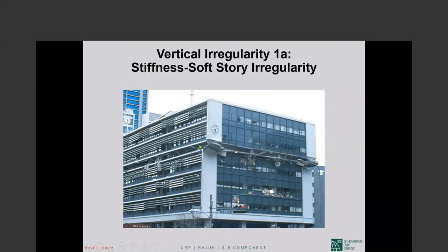And this was the first level with just reinforced concrete shear walls. So there was stiffness discontinuity at that level. There was higher stiffness below and lower stiffness above. The definition says less than story above, but it can be both ways. Anyway, you can see that there is a stiffness discontinuity, and the building failed right there, at that level.